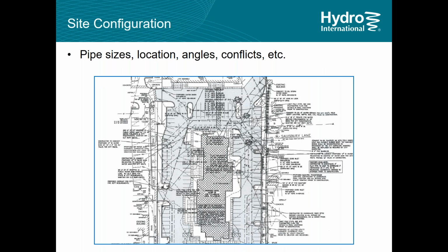And then you have to go to the real world and understand that sites can be complicated things. And when you start looking at the physical arrangement of the site, how much water runs in every direction, where all the pipes are, how deep the pipes are, where all the utilities are, and also where you need to place it for maintenance, a lot of consideration has to go into what system you use.